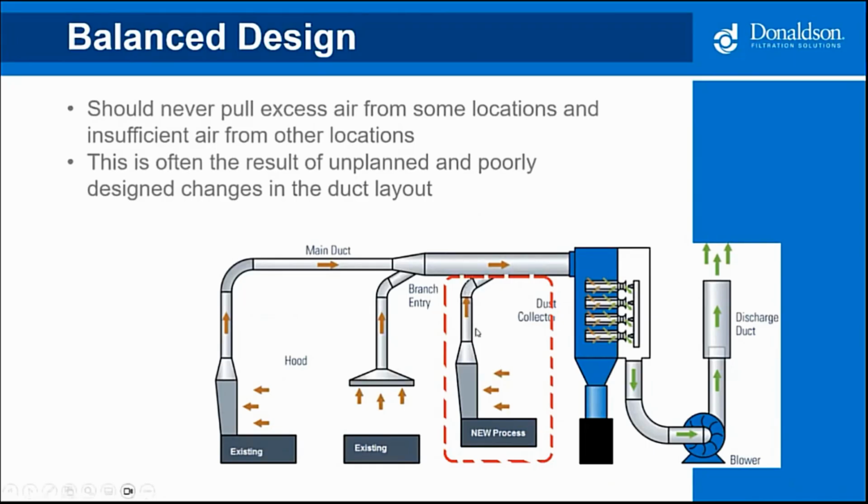So here's my number one recommendation to each of you. If and when you design an industrial ventilation system and you deliver that design to the end user, if they know they need to change it at some point in time, one, you can design future into it. Two, you can say, call us before you do it. And then you get with us, we can work together on making sure that whatever we do, it's done so that the system does remain balanced.